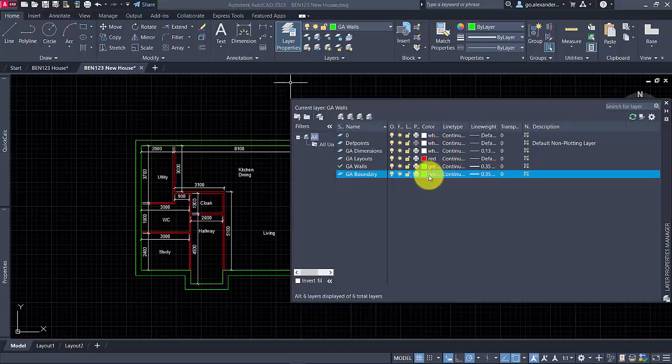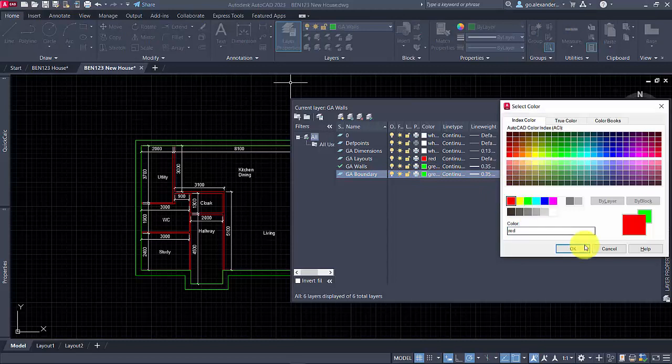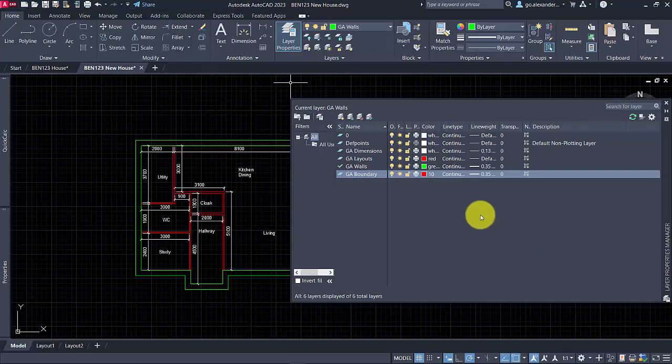I'm going to make that line red, index color 1. Although debatably you may want to make it one of these other colors so that it does print out in color at a later stage. Yeah, let's choose index color 10 actually. Make that layer current.